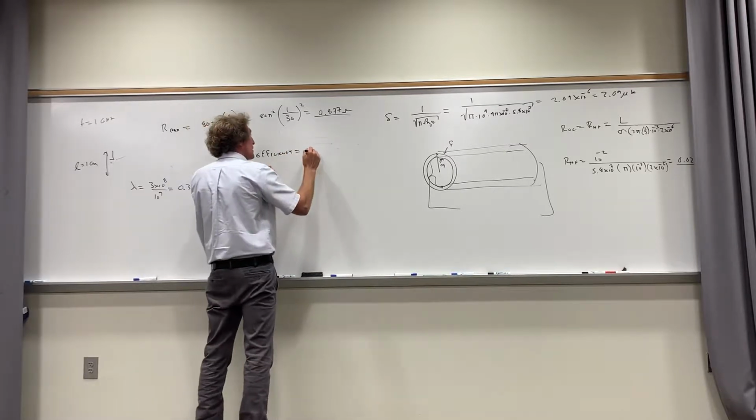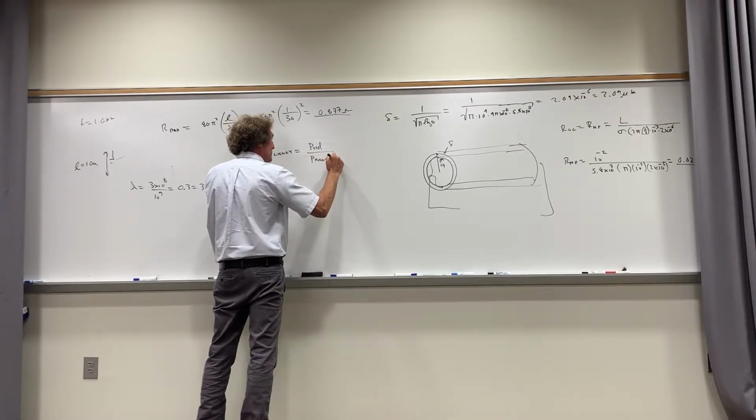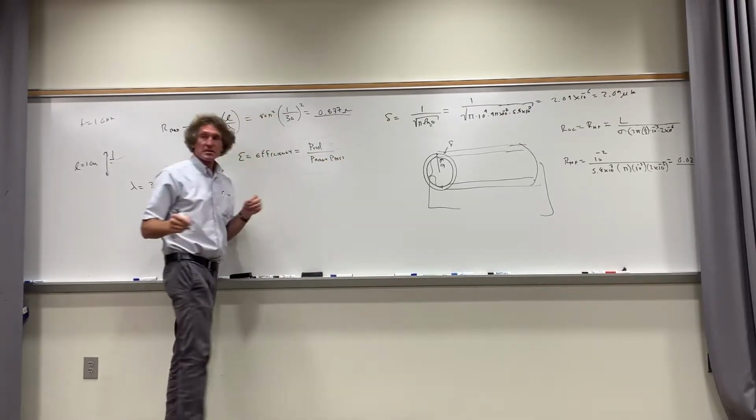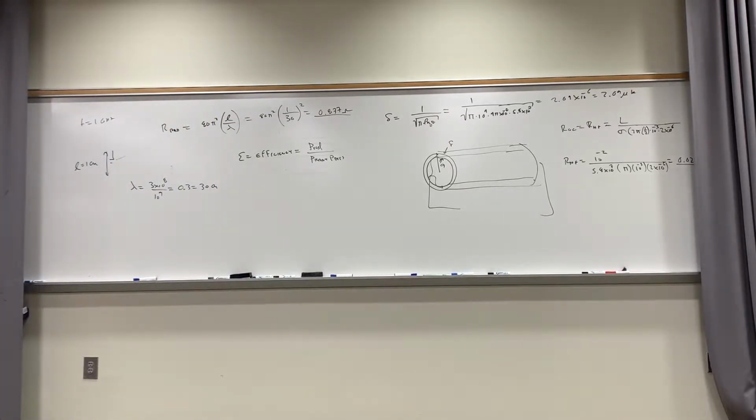That's equal to the power radiated over the total power radiated plus power dissipated. Follow me on this? Efficiency is always, if it's 1, it's always multiplied by 100. You could get percentage, but it's always total power radiated over power radiated plus power losses. So it's power dissipated by the resistive heating in this case. Does this make sense to everyone, class?